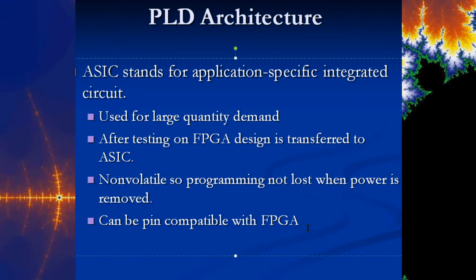Okay, this is super helpful too if it's pin compatible with the FPGA, because then you don't have to rewrite. All the pins are assigned on our board for what they are, right? And that's what the manufacturer came up with. Well, if we wanted to transfer that to an ASIC, we may have to readdress all the inputs and outputs to whatever this is. So it's nice when you can just transfer the whole thing over and then all of the inputs and outputs line up.